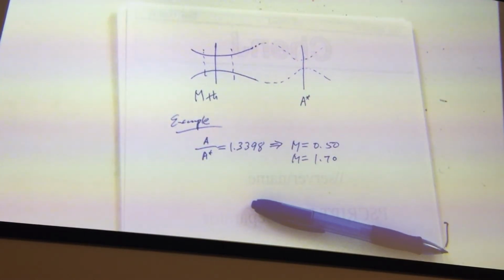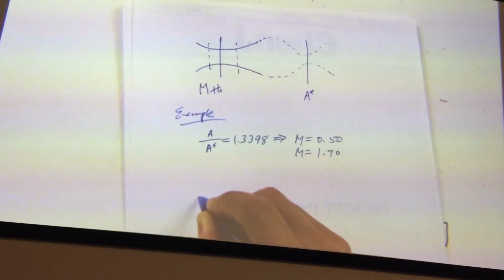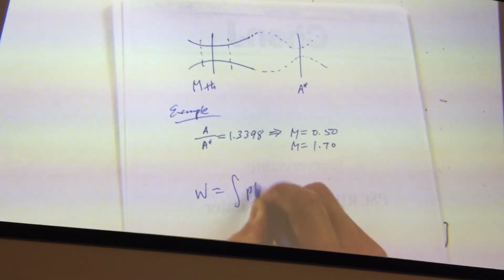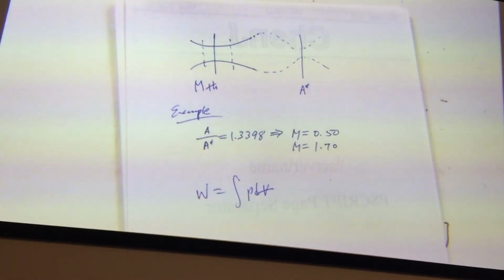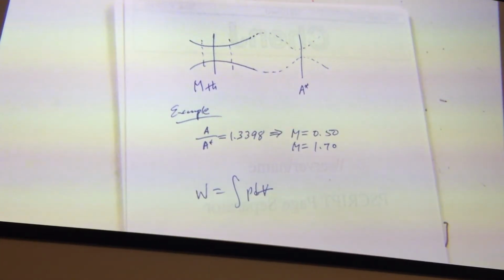And pressure, you think about it, is able to expand. And in thermodynamics, this is the PdV work, right? PdV work is equal to, right? Now you think about it, pressure in fluid flow is kind of like voltage in an electrical circuit because it drives the flow. So high pressure means a lot of ability to do work because you can expand.